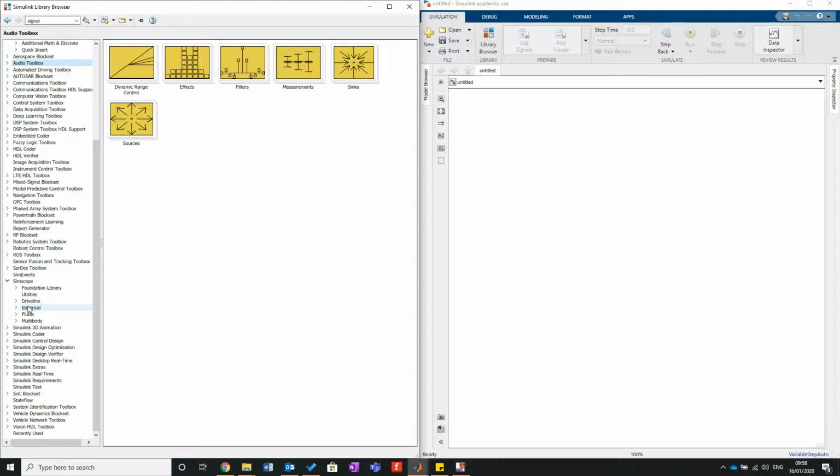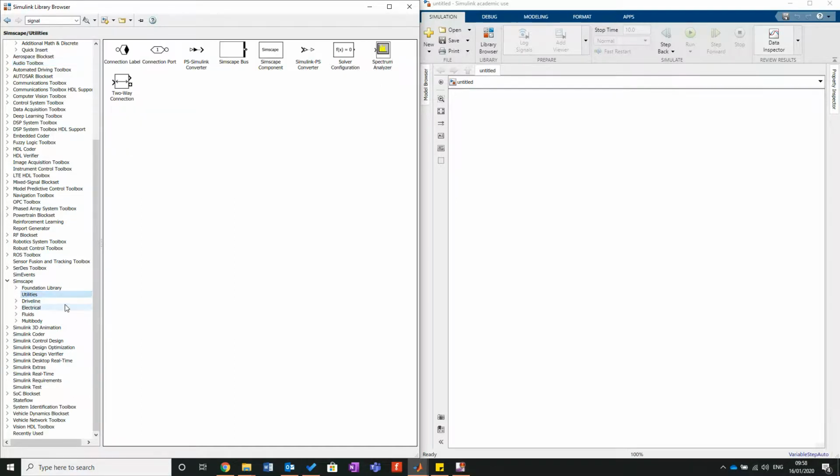Right, the first thing we need to do is establish a zero marker, so an origin. We need to establish a solver configuration. We need to establish a world frame, in essence where we will begin from. And also, we need gravity. For any budding physicists out there, this solver configuration allows us to use all of Matlab's ODEs dependent on your time settings.